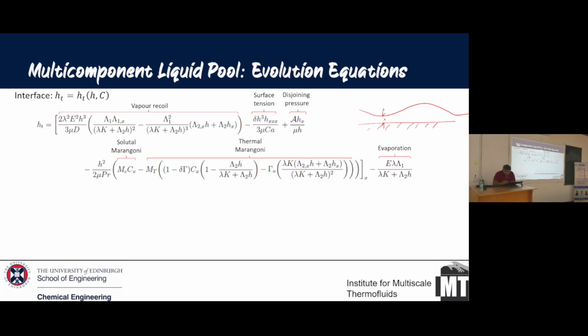Whenever it is tending to close to the wall, continuum approximation breaks down. If it's forming a kind of a contact line, if it's touching the surface, it's breaking the continuity of the equation there. That breaks down. So to avoid that, what I do is I put some kind of a disjoining pressure.